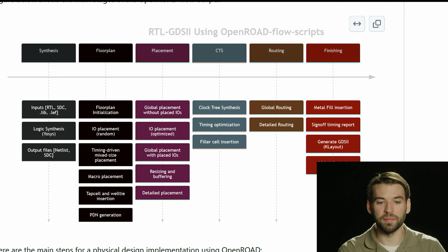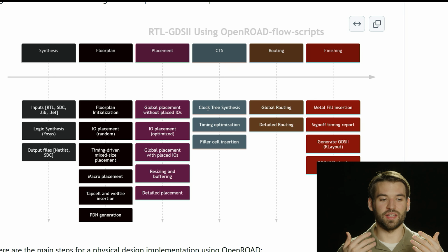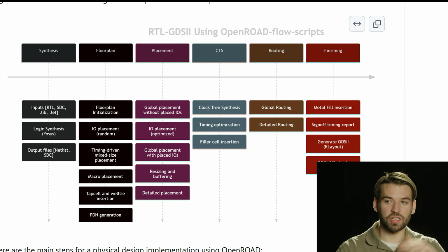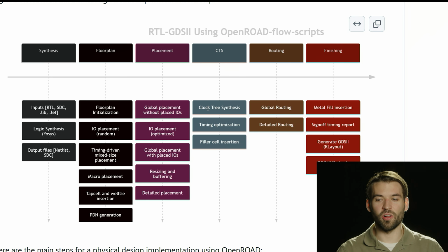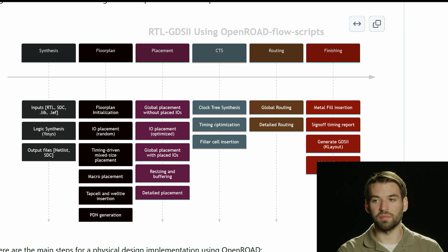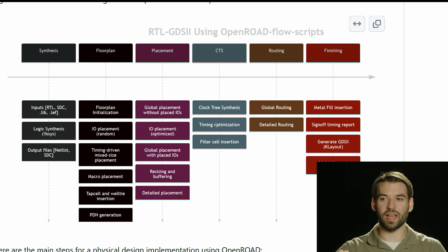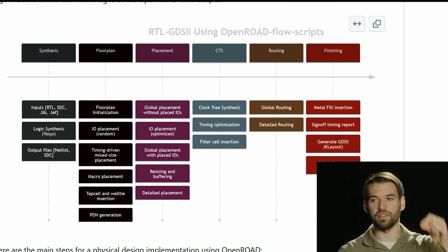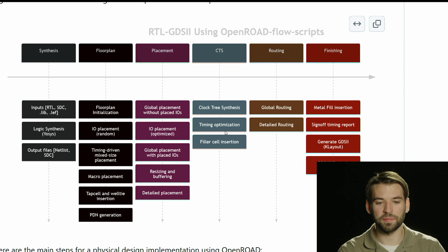Because we're working with wires, which also have an intrinsic delay, we need to construct this tree structure so that all of the endpoints of the tree are hopefully balanced, so that when you send a signal from the top of the tree down to any one of the leaf nodes, they all arrive at roughly the same time.